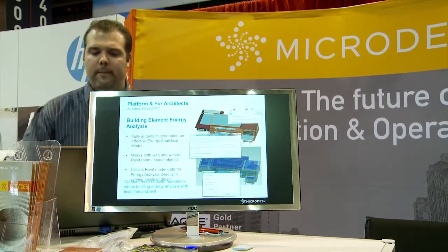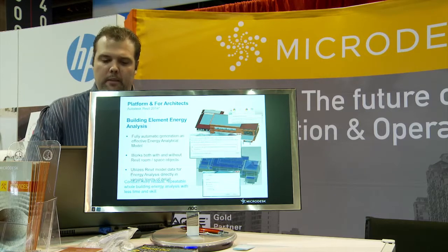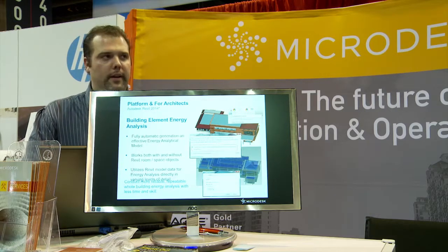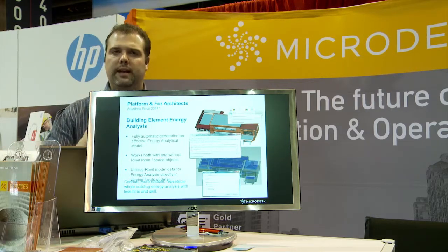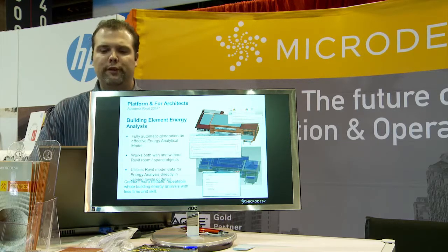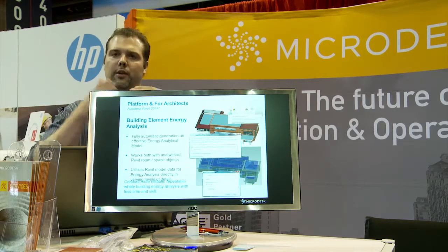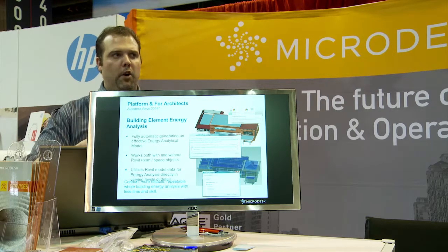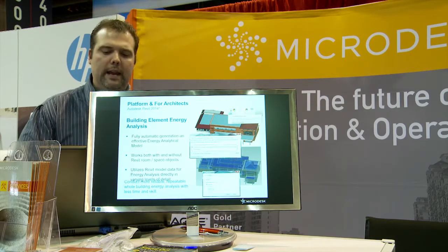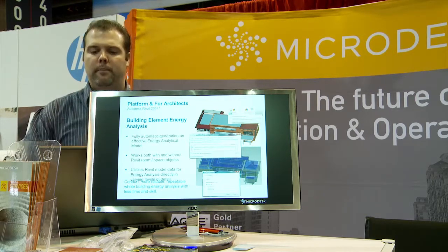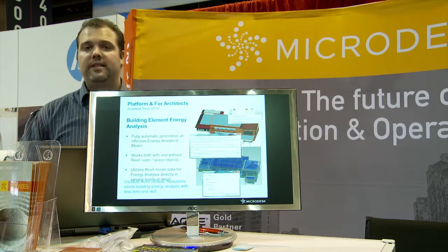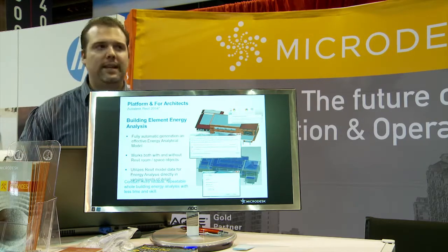And it requires a lot of management in terms of how the model is put together, but also how the connections between the elements work. Let's say if you have a sloped ceiling or a sloped roof, you will have to manually go into any areas that were a little more organic, and bound every part of the building, as well as integrating rooms in places that were not occupied.